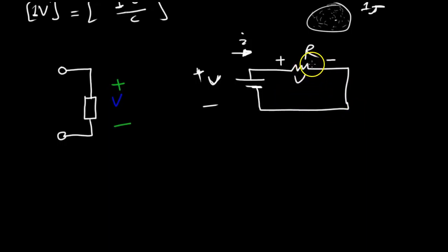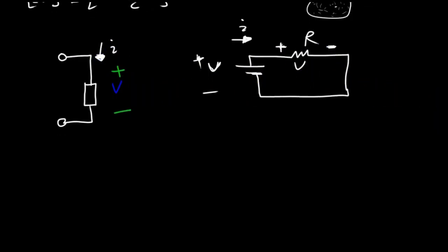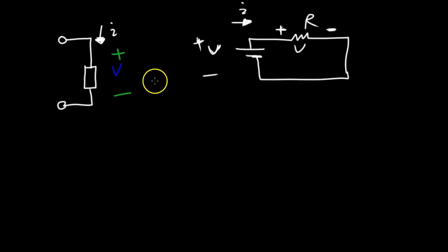So we're going to see some voltage across it, and the polarity indicates that current flows from the positive terminal of a voltage source towards the negative, from the higher potential to the lower potential. So we have this current going this way, and we have to make sure we check our signs and follow the passive sign convention that I just talked about.